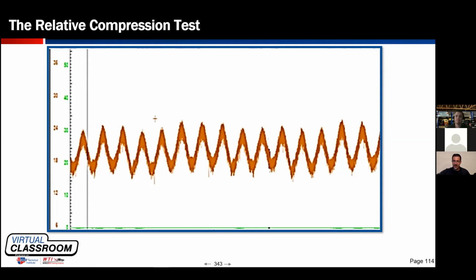So Dave, he's even more of a flat rate guy than I am, right? Dave doesn't even care that he doesn't have an ignition sync, or maybe he doesn't even know the firing order. It took him 10 seconds to put his amp probe around the battery cable and just hit the key. He saw all the cylinders were the same, so he said, you know what? I don't really care which one's cylinder number 3. It just doesn't matter. And sometimes that saves time to view things like that. But you learn to implement tests like this in time.